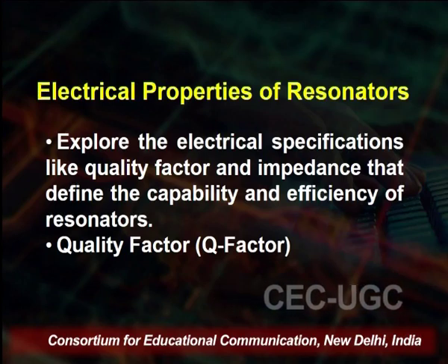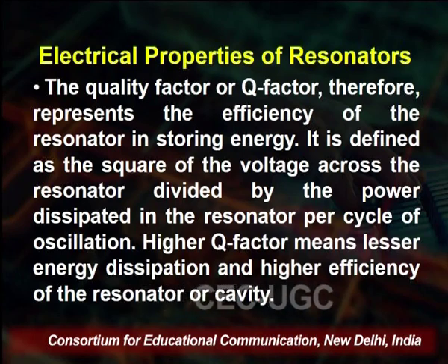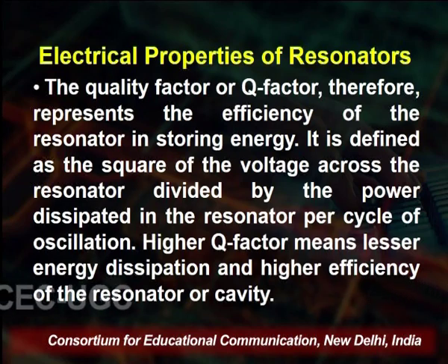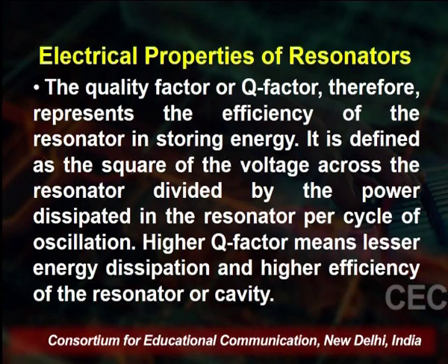So first is the quality factor, also represented by the Q factor. This quality factor represents the efficiency of the resonator in storing energy. It is defined as the square of the voltage across the resonator divided by the power dissipated in the resonator per cycle of the oscillation.